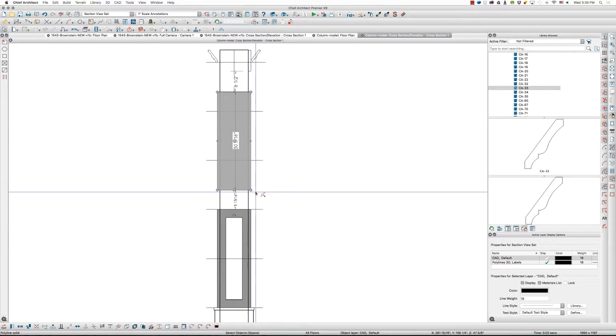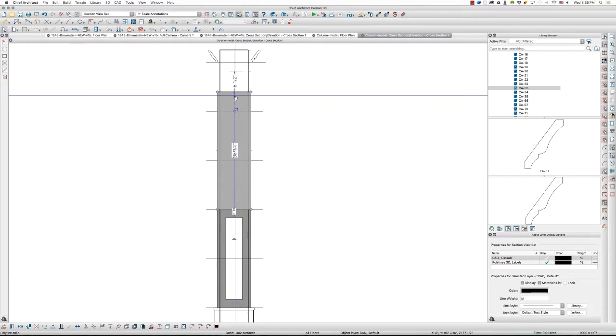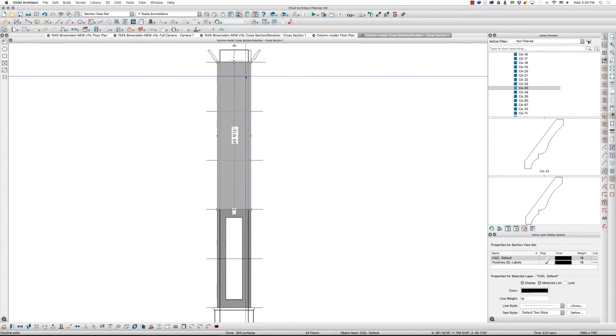That means I'm in concentric mode, and if I start pulling, I'm going to pull the top and the bottom the same dimension in my 2.5 inch jumps. Well, I don't want that really. So I'm going to go back to my default on the operations menu here, and just pull that down to this line, pull that up to this line.